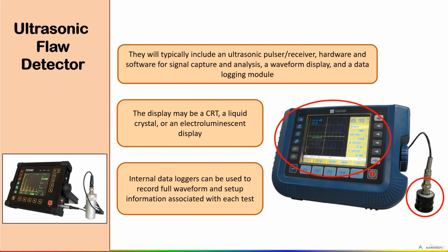Modern flaw detectors typically capture a waveform digitally and then perform various measurement and analysis functions on it. A clock or timer will be used to synchronize transducer pulses and provide distance calibration. Signal processing may be as simple as generation of a waveform display that shows signal amplitude versus time on a calibrated scale, or it can be as complex as sophisticated digital processing algorithms that incorporate distance amplitude correction and trigonometric calculations for angled sound path.